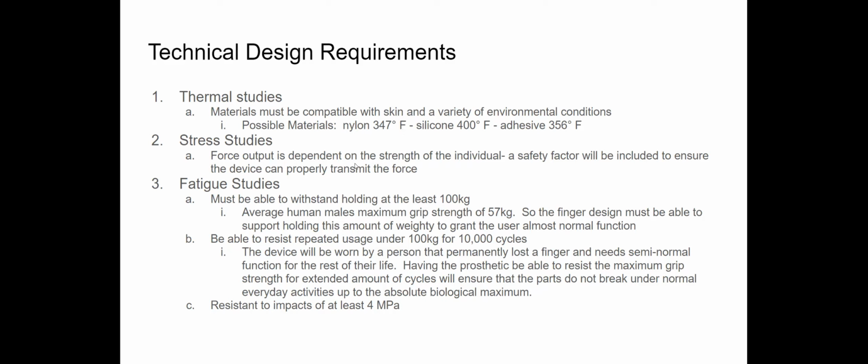And then we have our stress studies, which is for crushing, pulling, pushing of the finger, just to make sure that it can resist that. And then for our third one, we went with the fatigue study, which is kind of a derivative of the stress studies, where you're applying the stress study over and over and over again for a certain amount of cycles to see if it's going to break. And that is so that we could test for longevity.